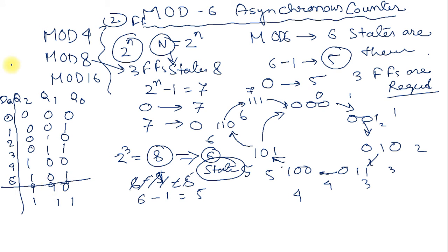Condition. So here, after this, we should direct the counter to be the initial condition, or 0. So the 6 and 7 states are ignored, omitted, or jumped; the counter does not count 6 and 7, and after 5 it should come to 0 once again.